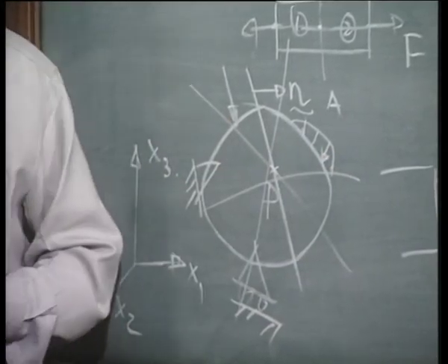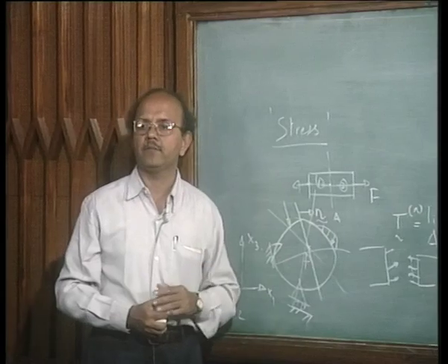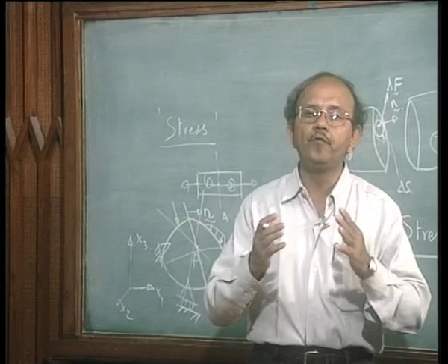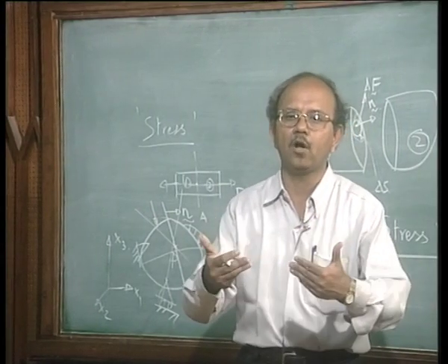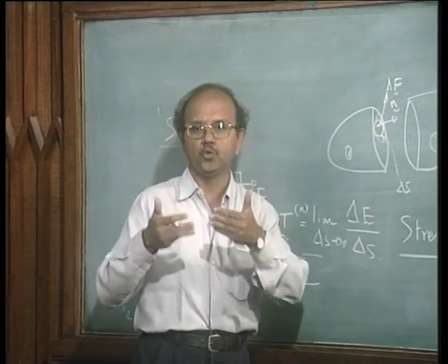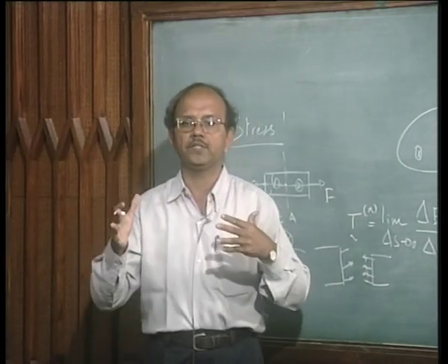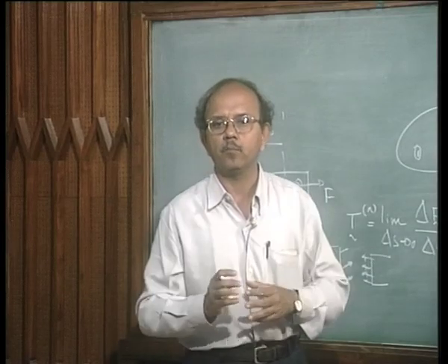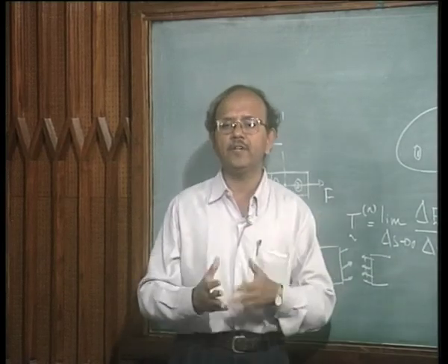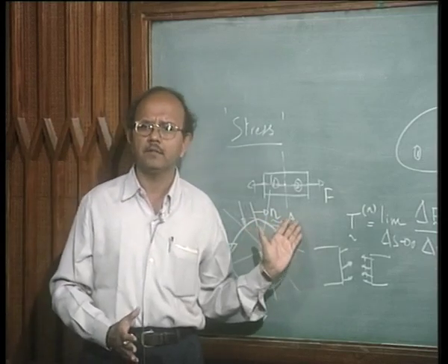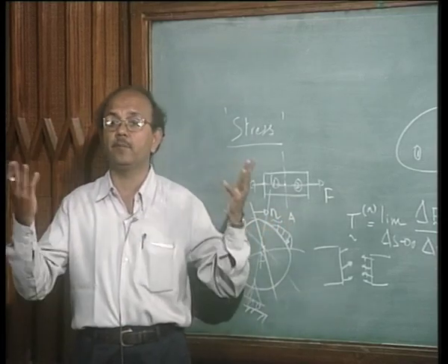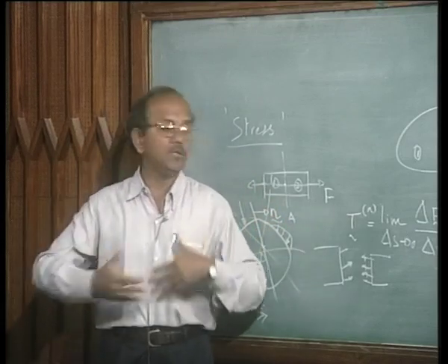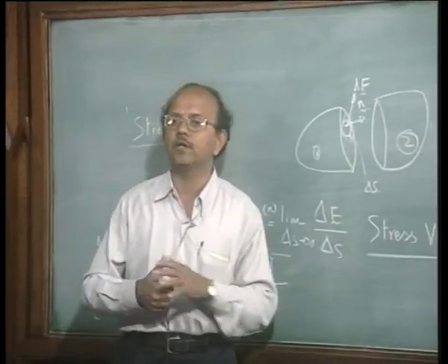Or in other words, this stress at a point P becomes meaningless because that is also wedded to the normal that you can draw, or the plane which you use to cut it into two pieces and look at the interaction at a small area around P. Is that clear? Clear. So infinite number of planes I can cut. So there are infinite number of values of stress, or infinite values of stress vectors that you would start talking about.